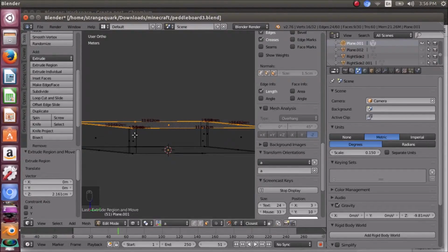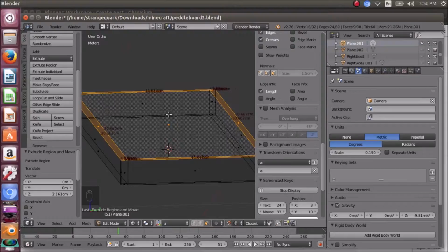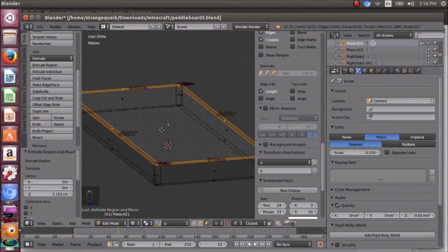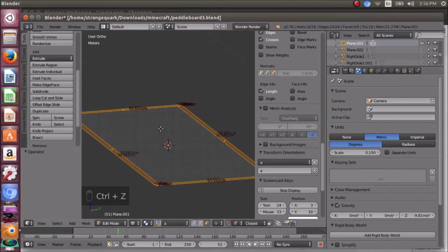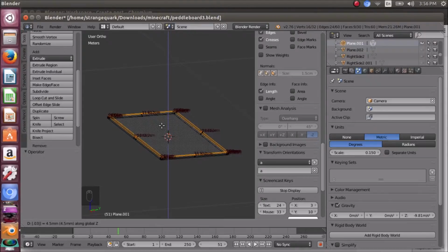So when you're doing extrusions of all of this stuff, you want to keep that in mind, incorporating the wall thickness. So I'm going to go ahead and back out the extrusion, and instead we'll extrude it on the Z by 0.03866. So we have already now the wall thickness of the sheet.